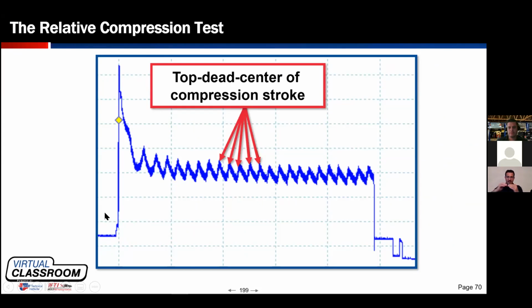As soon as it does engage, we know we now have current flowing through the starter windings, and we have this huge, huge spike here. I know you don't see any numbers reflecting the amplitude of this spike, but on any conventional 4 or 6 cylinder engine, Brent, I've seen 700-800 amps or more sometimes.